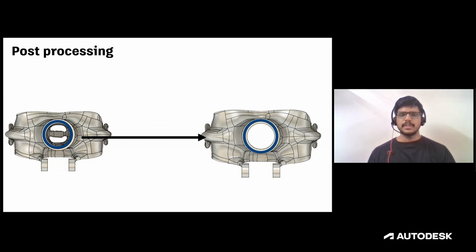The areas where the post processing has been done are highlighted in the picture, as you can see. Due to some unnecessary material available, the results get affected majorly during the analysis of the part. To avoid this major error, we decided to do the cleanup, or what you can call rework, in some places, by removing these unnecessary materials. One extra thing that must be noted here is that this unnecessary material can cost a lot during the manufacturing as well. As I said a while ago, the unnecessary material affects the analysis results. To know more about the differences in the results, please refer to our handout.